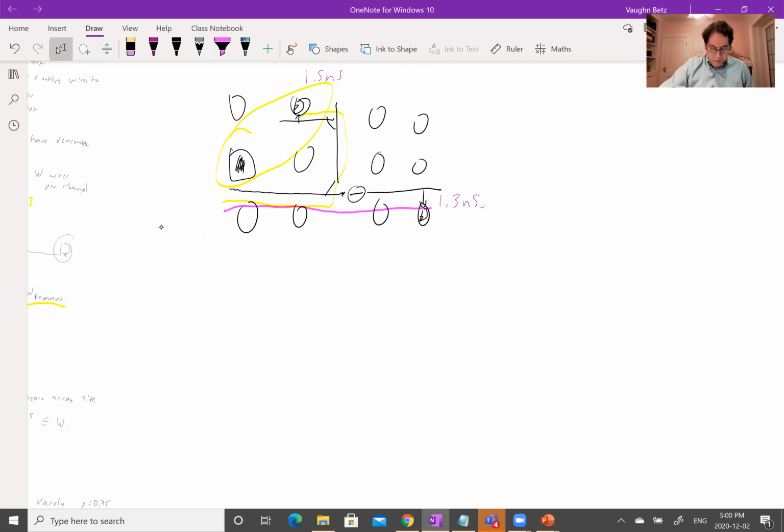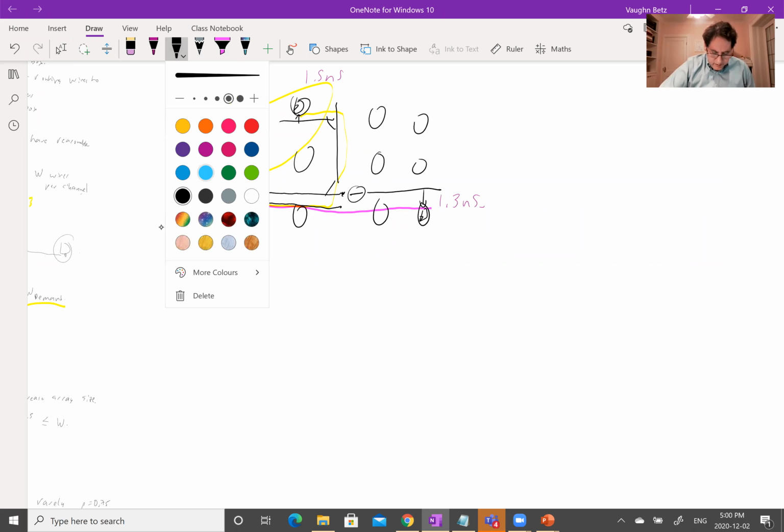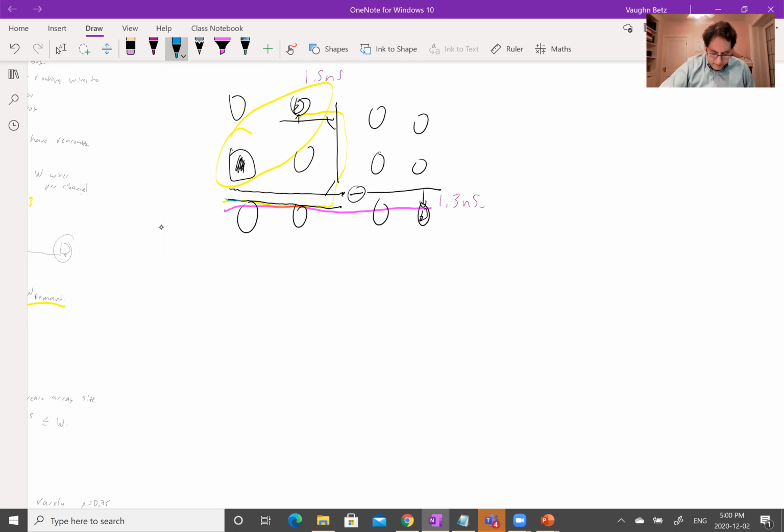So let's take my little route here, and I've basically gone in and created the best low skew pattern I could, given the regular routing algorithm. But there are other wires around. Okay, so there's another routing wire here that maybe some other block is using. Let me change my color here. Let's draw it in blue. And this other block is using that routing wire, so maybe it's using that routing wire to go over here and keep going off to somebody else here.